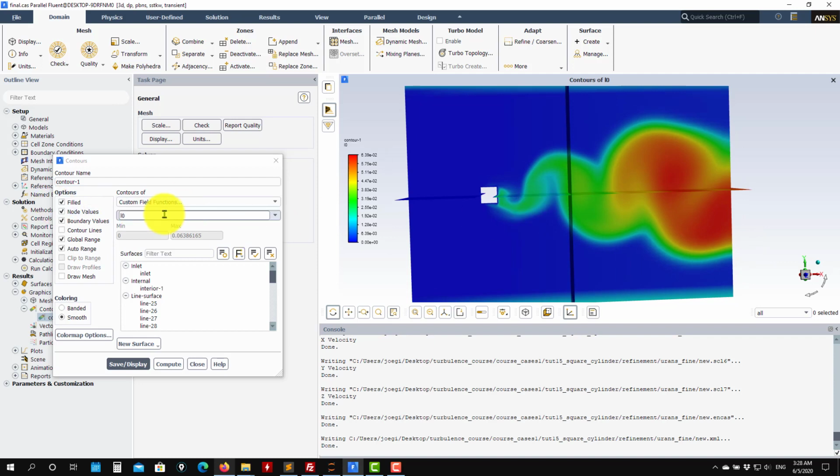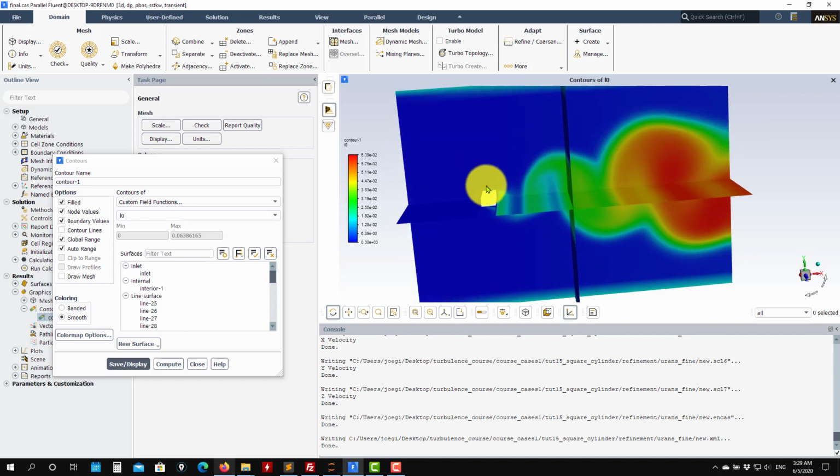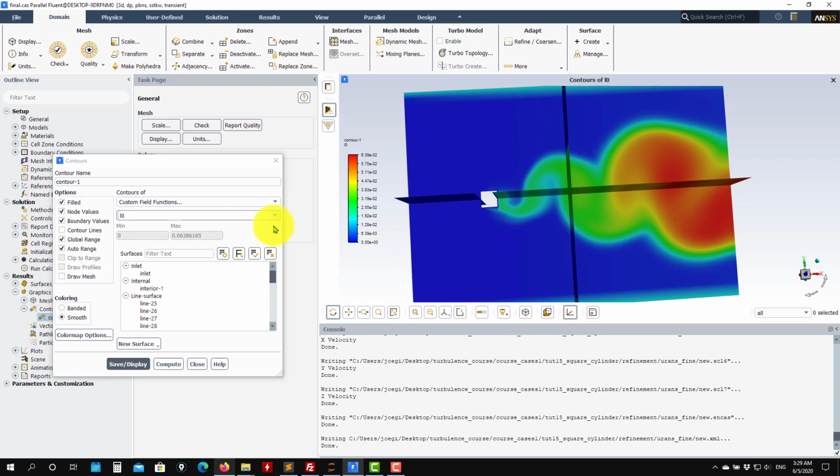So when you do this, it is recommended to compute the statistics of this one too. Usually in this case you will have this wake that moves and probably gives you a triangular cone here, and then when you do the meshing, you will put refinement there. In this case, I didn't compute it, but remember that computing it is highly recommended.